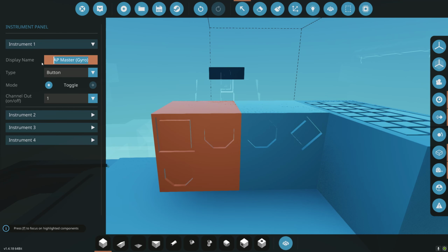So that'll be heading hold to bearing. All right, so what that's going to do is, say we're heading north and we want to go 090, and this says the waypoint's at 090. I want to make it so that if I press this button, it automatically makes the heading hold go to 090. All right, so that's set up.